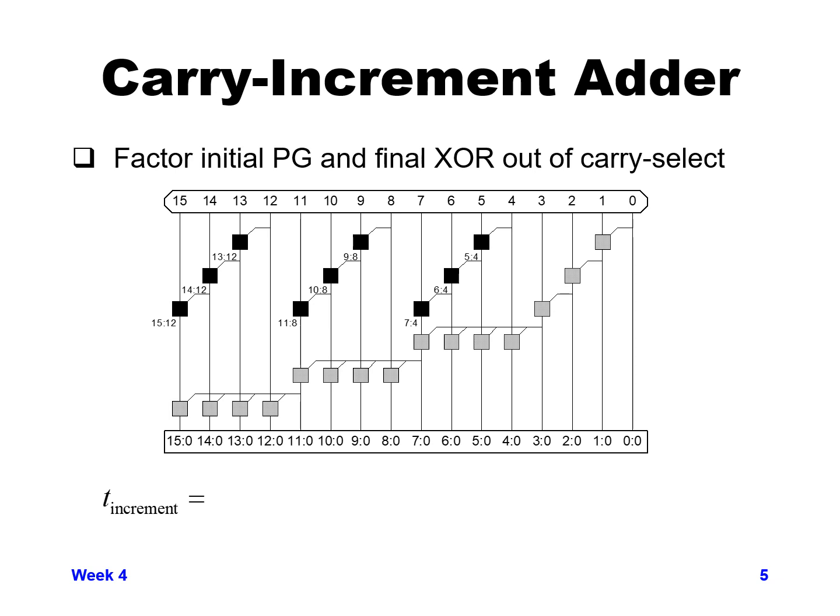The PG logic is shown in black, and the denotation of the carry in coming in and performing its function is in gray. So this is showing what we could get for the delay through the full adder if we did that functionality for a carry increment adder.